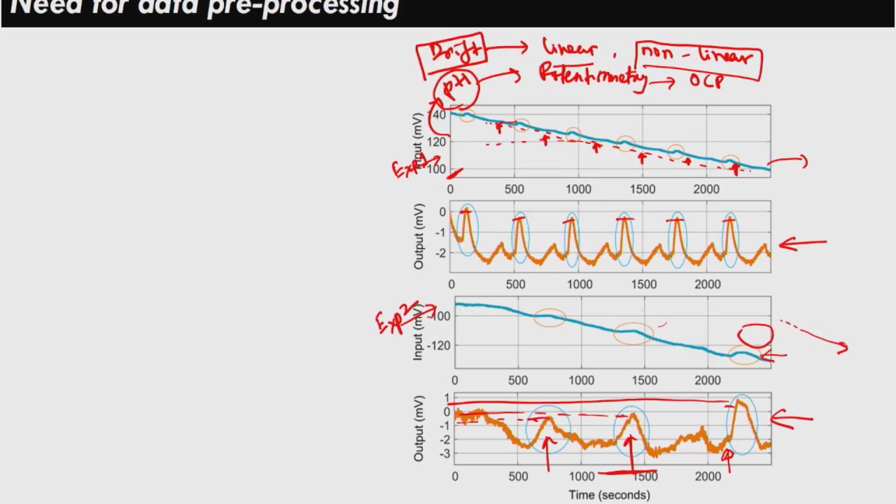So, you have to do something in real time so that you are able to distinguish between drift and signal. Let us say in addition to this bump, here it suddenly goes up. This is non-specific, it is not due to injection, or it could be an artifact that we got while cleaning the signal. You can see that there are two ways in which drift can go. It can be linear unidirectional, or it can be non-linear, and of course, it can go in either direction, positive or negative. So, how do we deal with that?